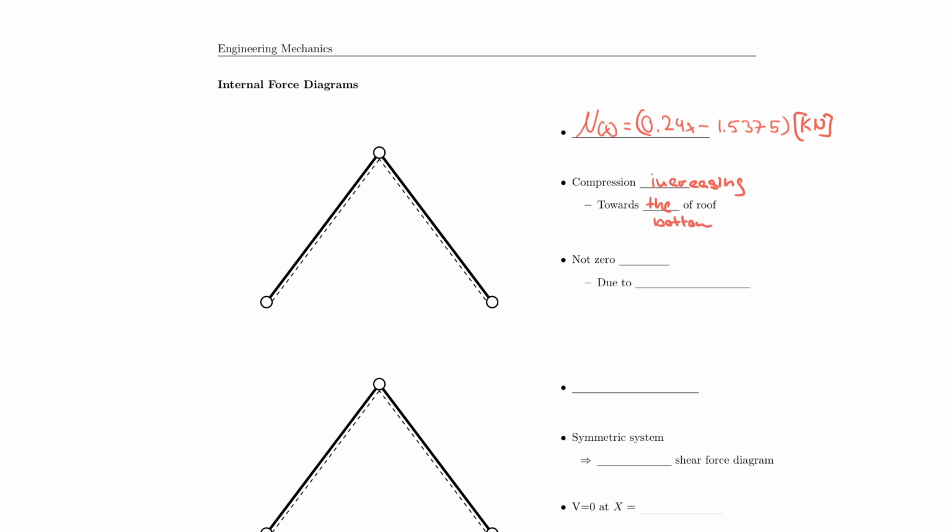Of the roof, and then it's also not zero at the top because we have the pitch of the roof due to the angle. So that hasn't changed. In fact, if you paid very close attention, you see that this equation, except that the numbers are a little bit different, has the same concept as we had for the self-weight. And this is on purpose here for educational reasons, right? I used the 500 and the 500.